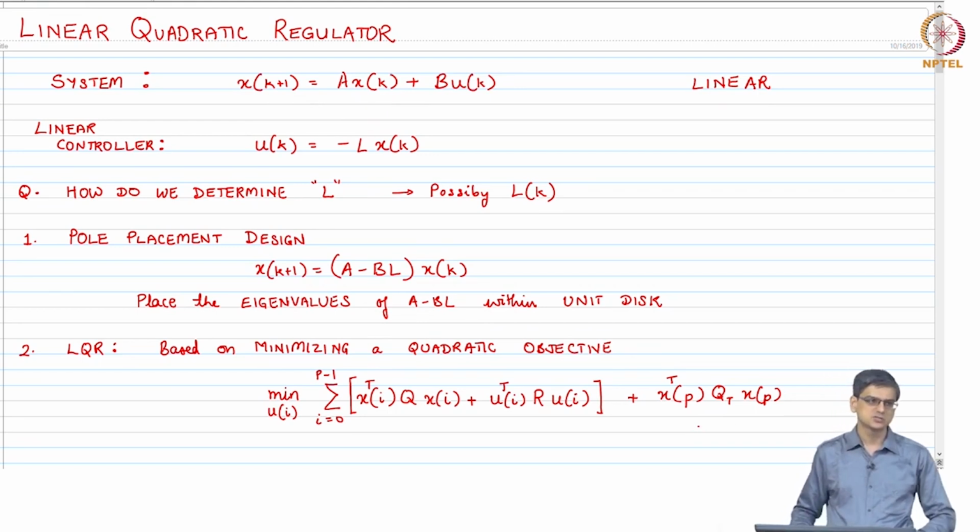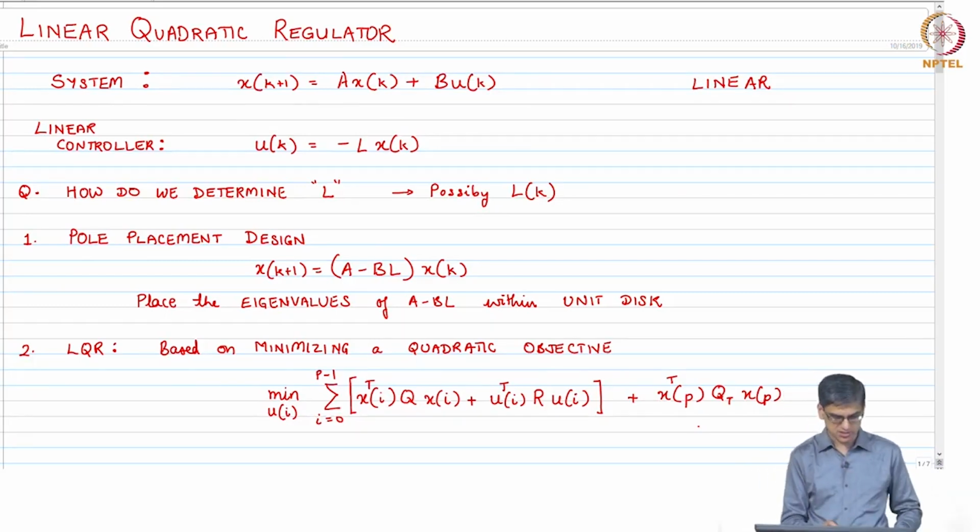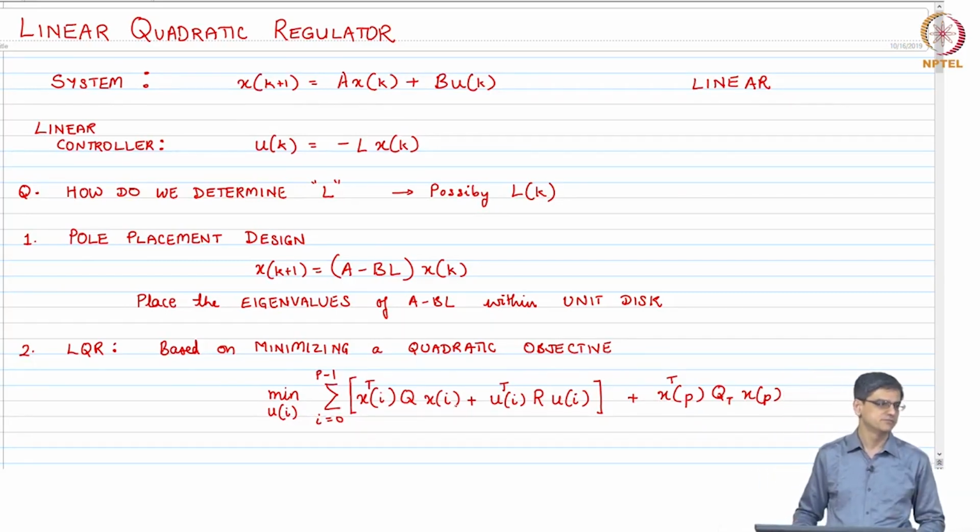The other difference is MPC came more from a practical viewpoint. So, that is why we said that within the summation itself Q and R could possibly vary, right. In the standard LQR you have Q and R remaining the constant matrices within the entire horizon. Okay.